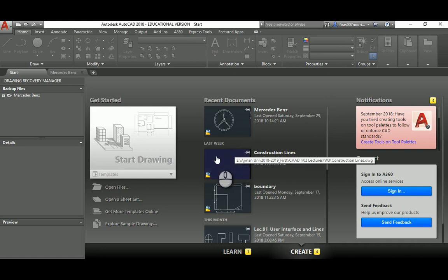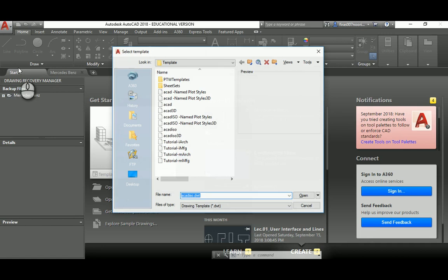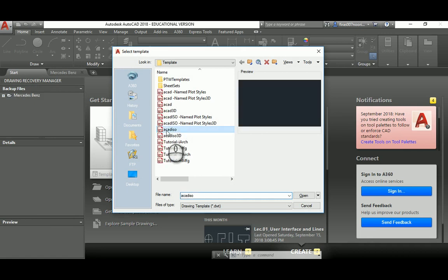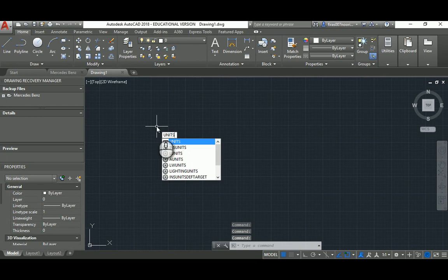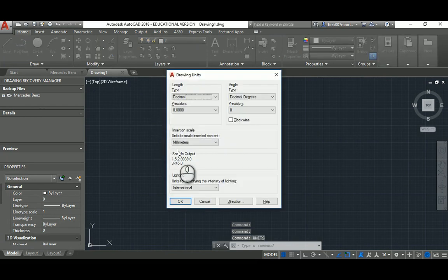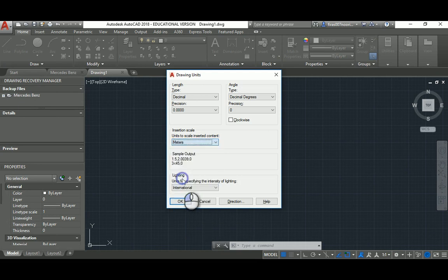Today I'm going to show you a basic introduction to the AutoCAD basic drawing tools. In our lecture today, it's lecture 2, third part. Basically, we're going to go to the application menu and start a new file. Then we pick AutoCAD ISO here. We need to check the units again and decide if we want them to be millimeters or meters. Maybe we can pick meters here.